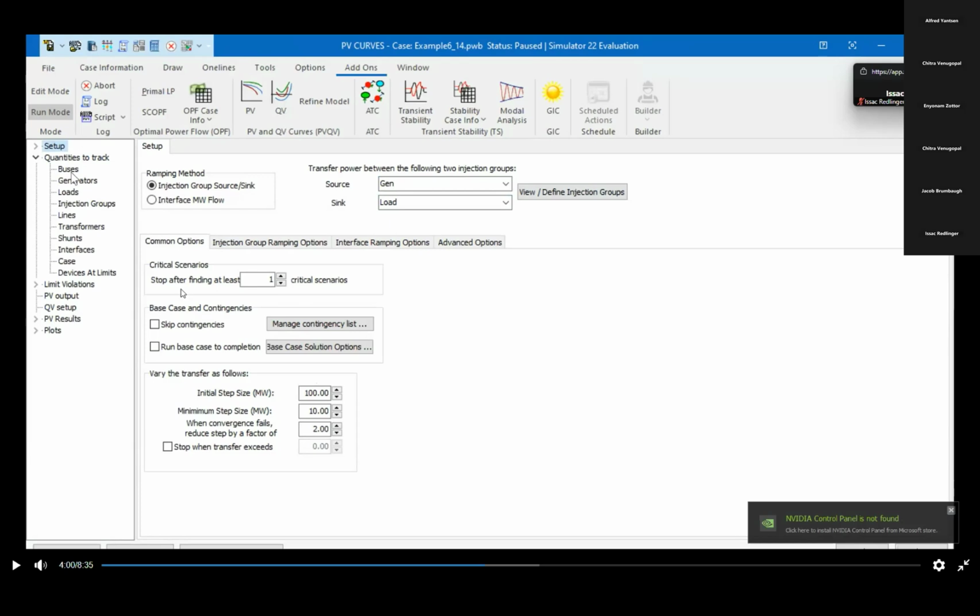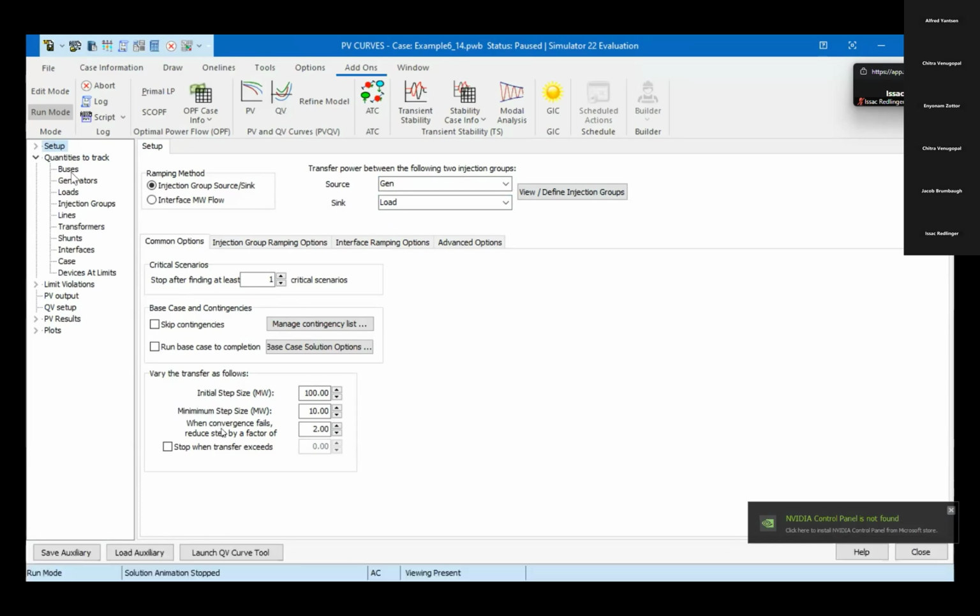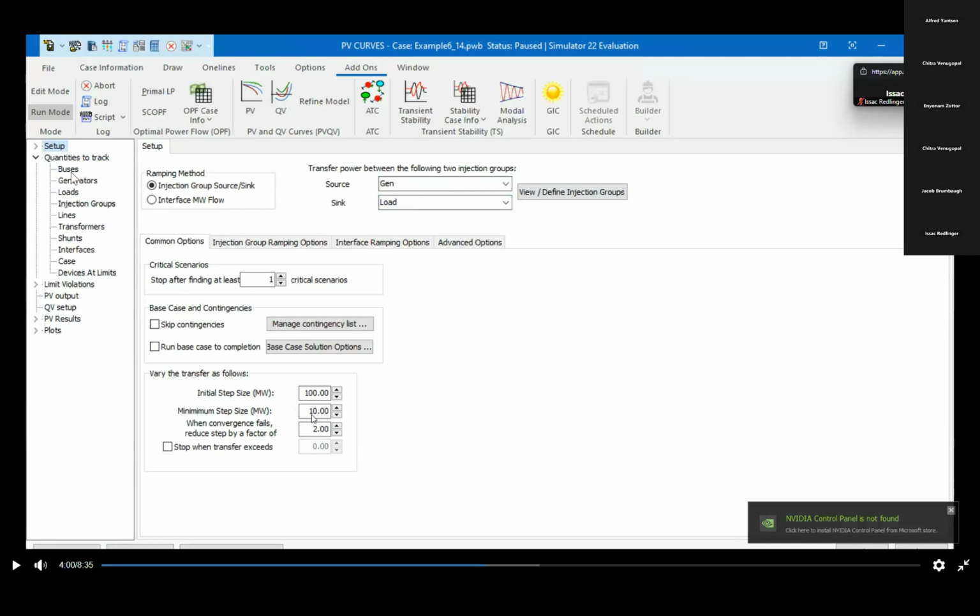These are the common points. These are mathematical settings, like how many steps it should run, just as with the Gauss-Seidel method, where we decided how many iterations to do. Here we specify how many steps we need, what the maximum number of steps is, and what the convergence tolerance is. You can change these, play with them and see how the results work.